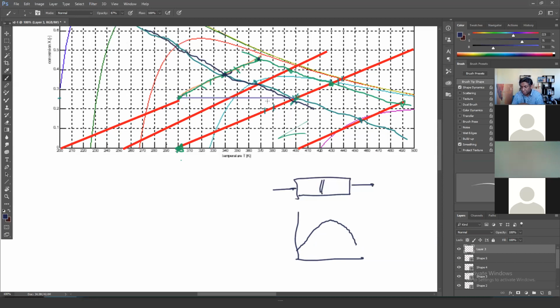So the suggested choices in the question were not random. Those are actually the best choices you can make if you have a CSTR in series with the PFR. In the CSTR case, you set your whole reactor on the maximum rate. If you consider all the fluid in the CSTR, if you take packets in that fluid, every single packet will be sitting and happily carrying on at that nice high rate.